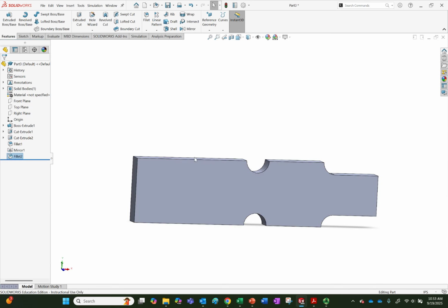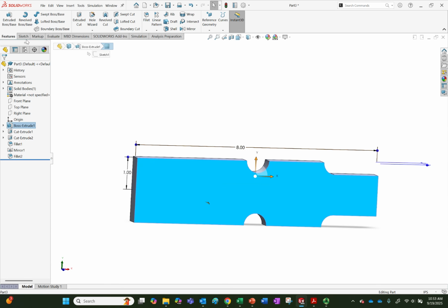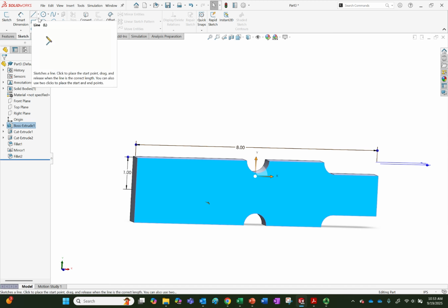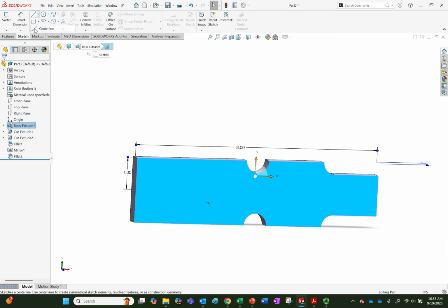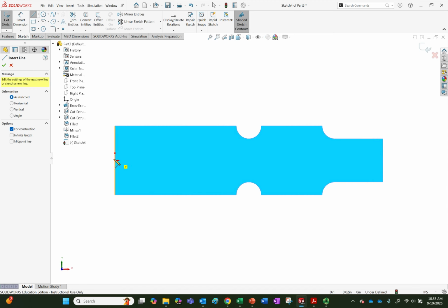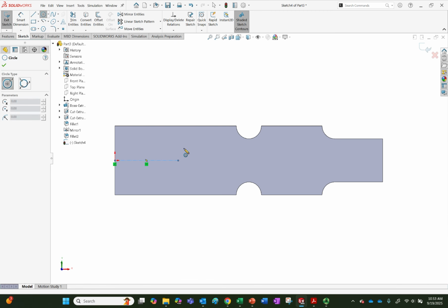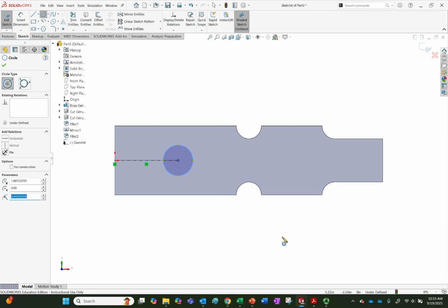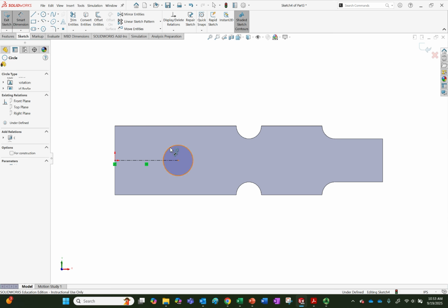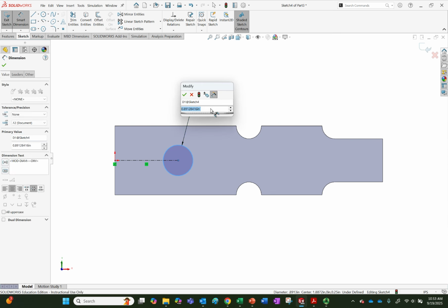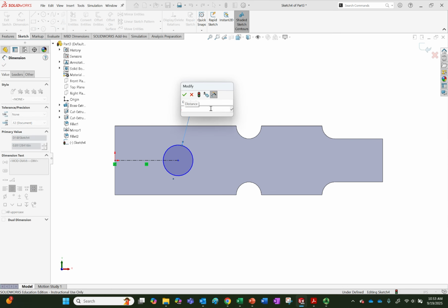Okay. And then lastly, I'm going to put the hole onto it. And it's probably easiest to use a construction line. So I made that right here. And this should be 3/4 of an inch, right? Because they all should have the same value, essential radius, 0.75.